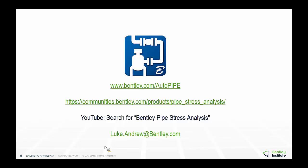Whatever the deflections are calculated to be, whether they're small or large, it makes no matter what is presented there. Just keep in mind that most of the calculations are assumed to be for, quote-unquote, small deflections. So if you're having some large deflections in your pipe, there's probably some sort of issue with your model, so you should probably be investigating those kinds of things.